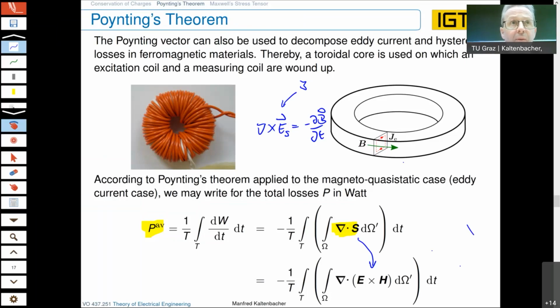Here, any irrotational part will be cancelled out by the curl. So we can write that this solenoidal part also of the current density, which is very often written with the index E for eddy current, clearly follows the classical Ohm's law: due to the conductivity of the material, the gamma, we get a relation between this eddy current density, which will go within the material, and the solenoidal part of the electric field, which itself occurs due to the time-changing magnetic field.